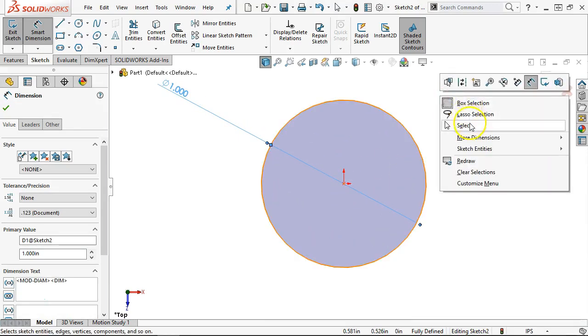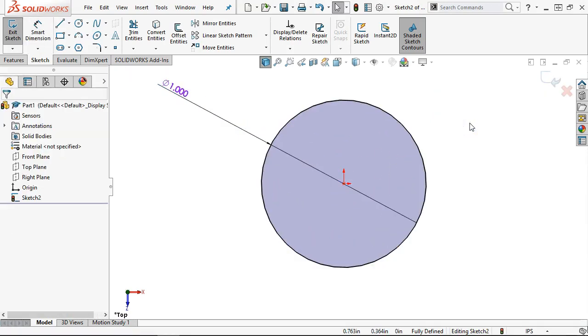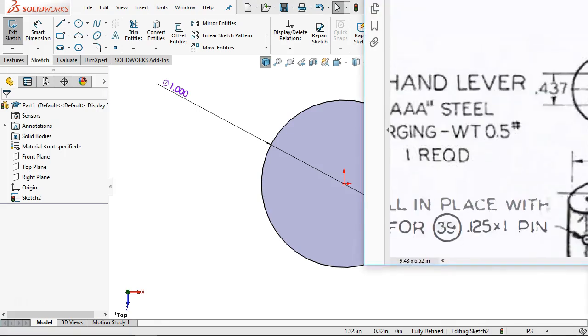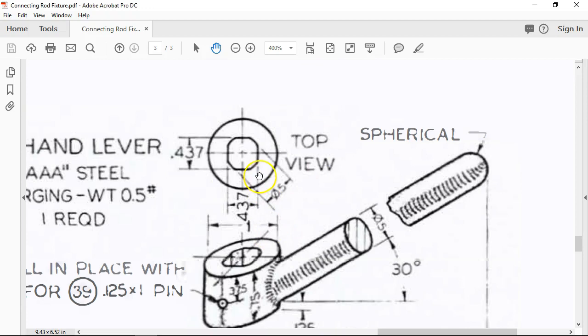All right, then the question becomes, do I go ahead with the extrusion, or do I put the, let's see, what would that be? I would call it just the broach, the intersecting, the mating geometry to the screw. Do I go ahead and put that in the same sketch? Well, this is simple enough that there's not a real reason, and probably not going to change. The issue here is with the angles knocked off the sides. This is going to have to be broached.